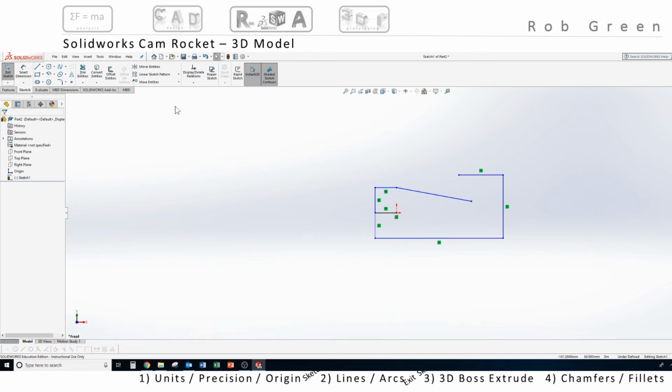So now I'm going to use the offset command, and I am going to come up here without anything selected and click offset. In my properties, I'm going to enter 59 millimeters because I want to create the bottom horizontal line. I clicked over here in my properties, or I could have hit enter, and I want to uncheck the option that says select chain and uncheck the option that says add dimension.